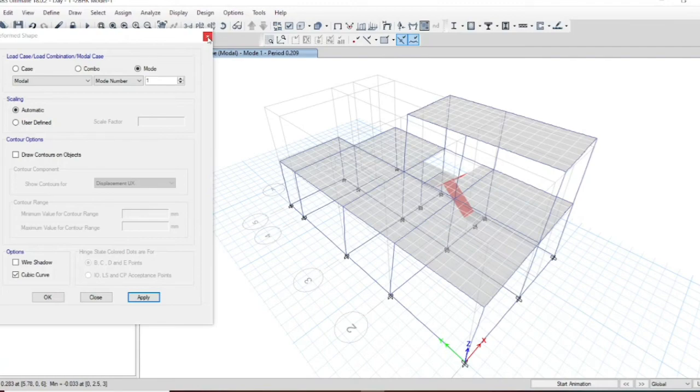Lateral loads and time variant loads are called dynamic loads. If the load is changing with time, for example, wind will blow at a particular speed in one state of time. At night you will have high wind speed. In certain months you will have different wind speed, like that. It changes according to time. But dead load, live load, super dead load will not change. It is constant. So dynamic load is time variant load. Due to time, if you have lesser or higher loads, then it is known as time variant.